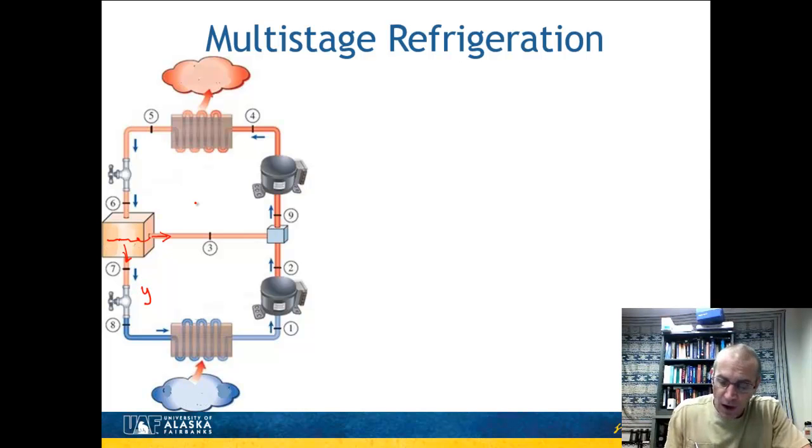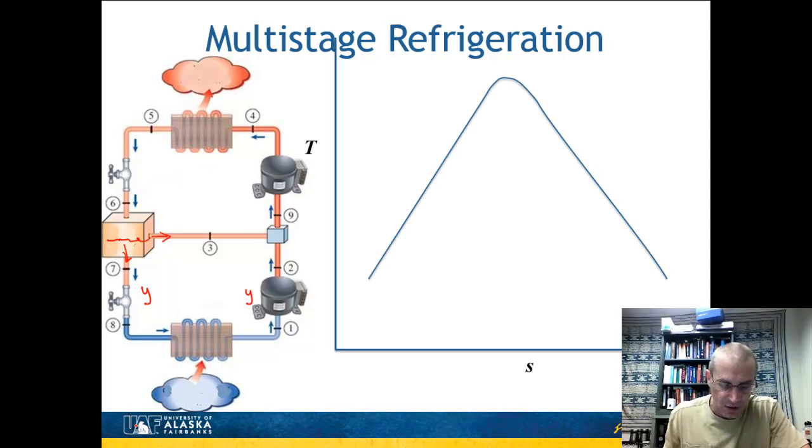the complete material that's operating through the upper stages of the cycle. So one of the things that makes this a little different is that it's a little simpler, because there's only one type of fluid that you need to run through. And since this bottom stage compressor is only running the fraction y, it often has a lower power requirement. However, they tend to be fairly similar to cascade refrigeration, and you'll see both types used depending on the particular temperatures that are necessary for the application.